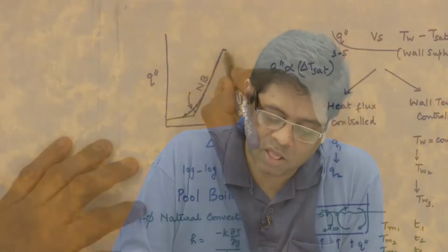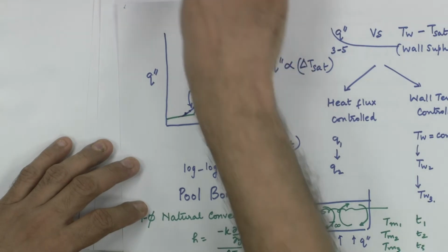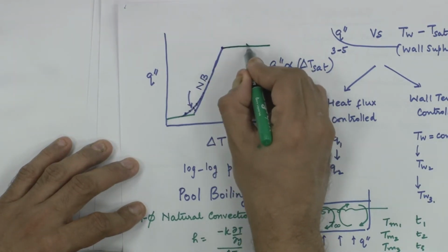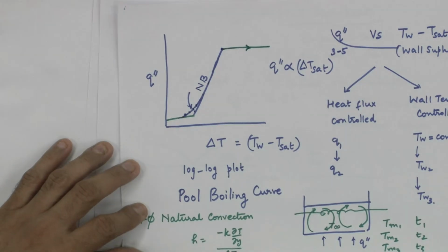So when no water is there in the vessel, the wall temperature will start to increase rapidly, and that increase is what you would see here. Even for a small change in the heat flux, the wall temperature will rise appreciably. This may not be so clear in this pool experiment.